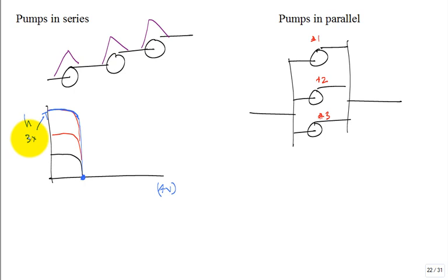Where the shutoff head is 3 times higher. So if I actually close the valve right here, I'd have the shutoff head for the first pump, second pump, and the third pump trying to open that valve and push through that valve.